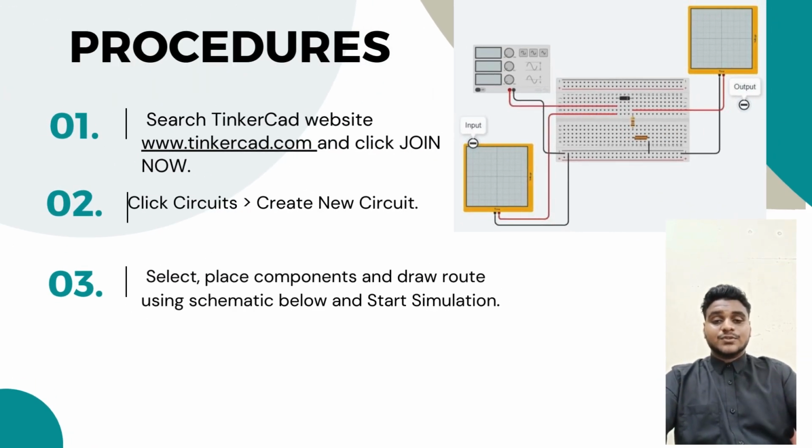And this proceeds to the procedures. For the procedures, first we search for the Tinkercad website, www.tinkercad.com, and click join now. Second, click circuits and create a new circuit. Third, select and place components and draw the route using the schematic below, and start the simulation as shown in the slide.